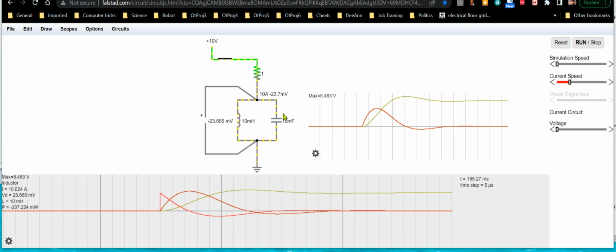but it'll allow really high frequencies. So if you had 30 hertz, let alone 300 or 3000 hertz flowing through it, the voltage across the capacitor would actually be increasingly small. But inductors don't like high frequencies, so the voltage across it, its resistance, what they call reactance, would increase, whereas the reactance of the capacitor decreases.